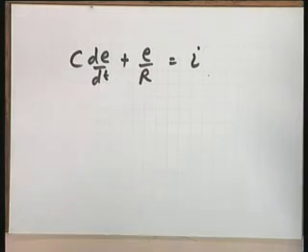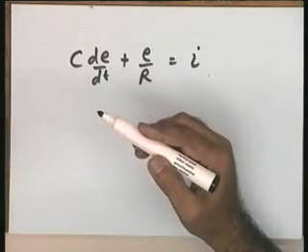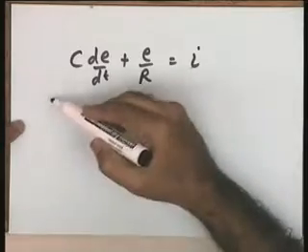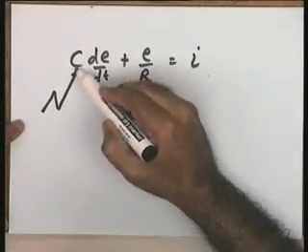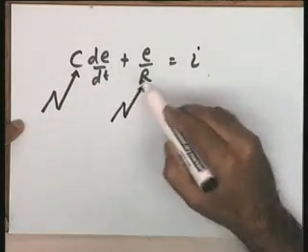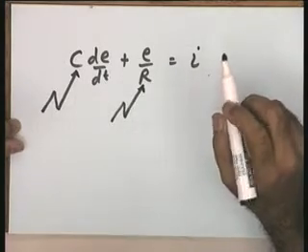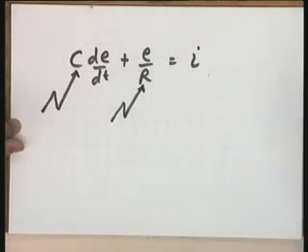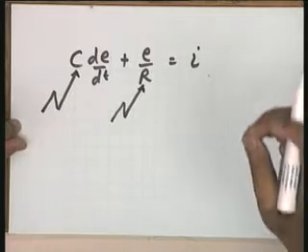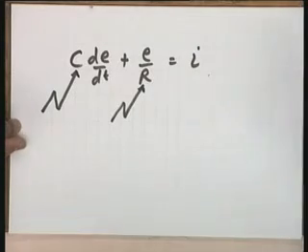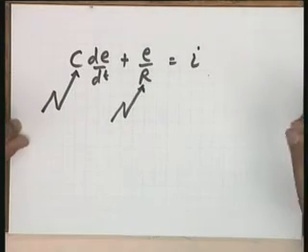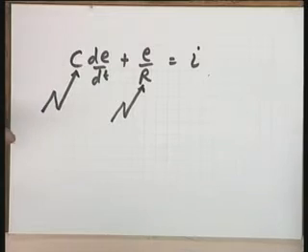at least in terms of developing the model. And therefore, from now onwards, as I made a statement in the case of thermal systems, I will be mostly referring to C and R as the two parameters of the liquid level system. Assuming that, in terms of manufacturer's data or your own experiments conducted on the system, you will be able to determine these parameters R and C.